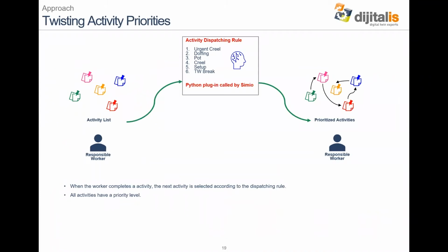One important thing in the simulation model is that whenever a worker completes its assigned activity, it looks at all the waiting activities. There might be different activities as listed here. It could be a setup activity, or it could be any of the 6 main groups of activities. Here we had an additional module attached to the Simio model, prepared in the Python language. It runs a prioritization algorithm and gets the result back to Simio, and then Simio runs a simulation and the operator goes to the next activity, which is determined by its priorities.